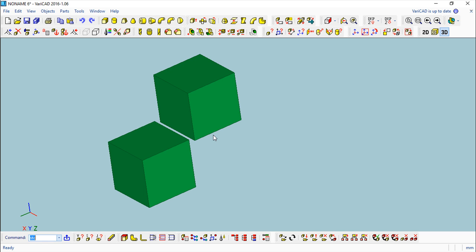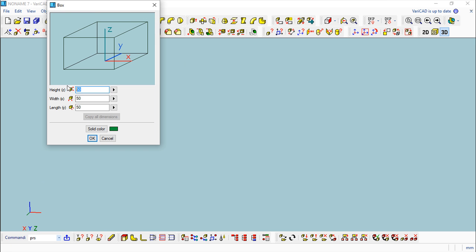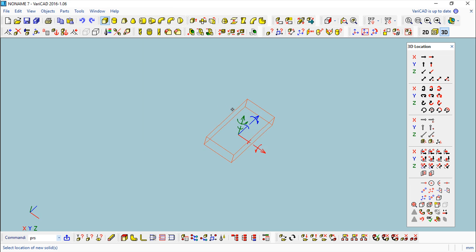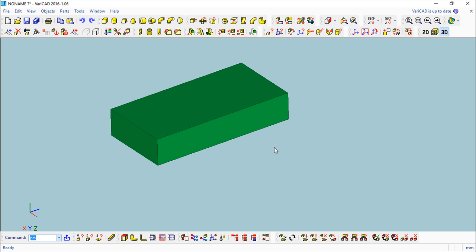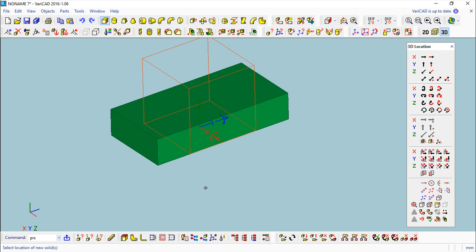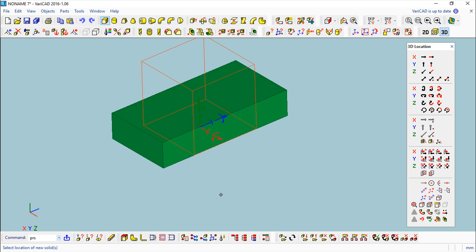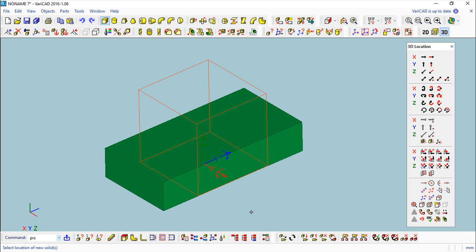Okay, let us make a very quick example of the possibilities. Again, let us make one very simple solid, a box with different values for each one of the axes. And now I will create one additional solid and will apply something that we call additional rotation. The additional rotation is used to apply an angular constraint.